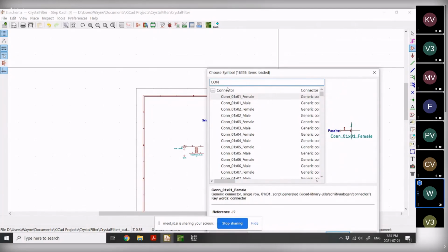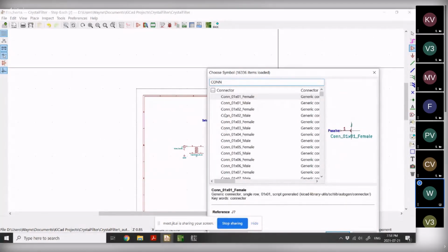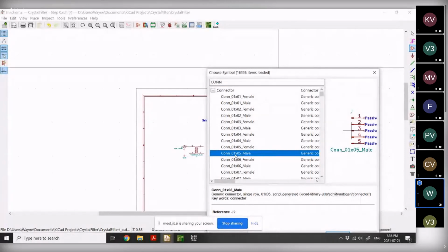And in the connector, I have a couple of things. Actually, I have lots of things in connectors. These 1 or 2 or 5 pin connectors, these are male or female type connectors. So these are the standard pin connectors, pin headers that you're used to. One thing I have to make clear here is that this logical schema element is not the component footprint. The footprint could be 2.54 millimeters apart, 5 millimeters apart, or something different than that. It's not really the component. You have to do a separate step to find that.